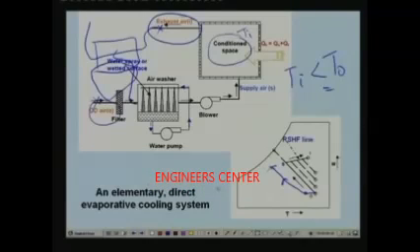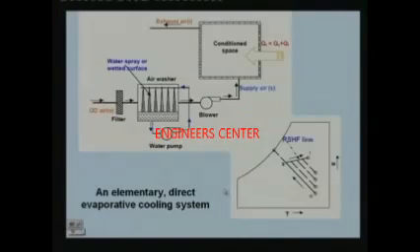Of course, achieving good heat exchanger effectiveness using air to air kind of a heat exchanger is very difficult, because you have to have large surface area, etc. That means you have to use a compact heat exchanger if you want to have good effectiveness. Okay, so you have to see the benefit versus the cost involved. Okay, but in principle this is a simple modification which can give a certain improvement.